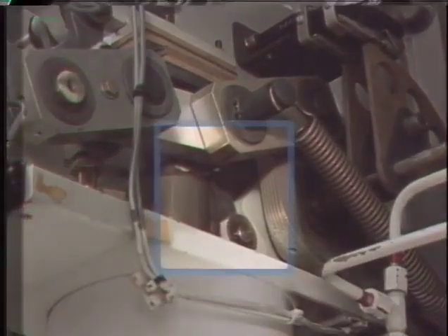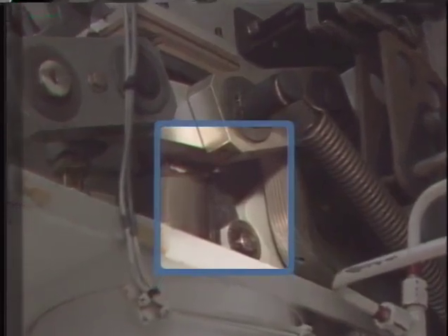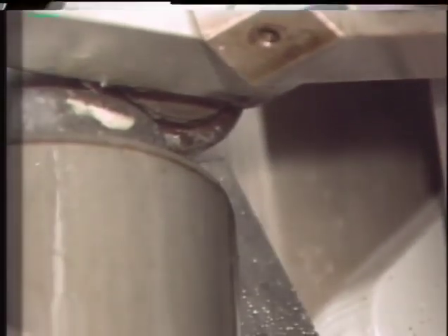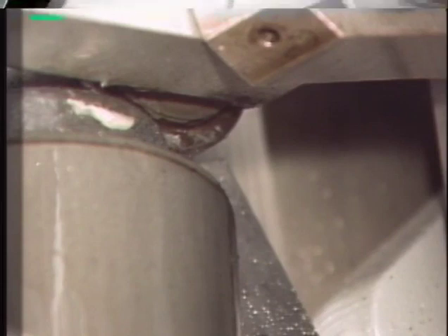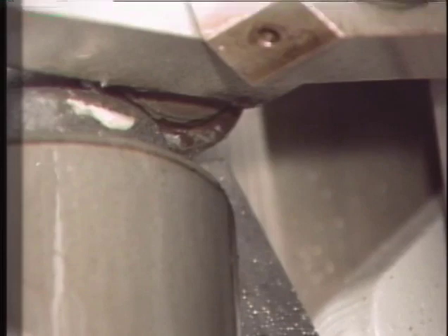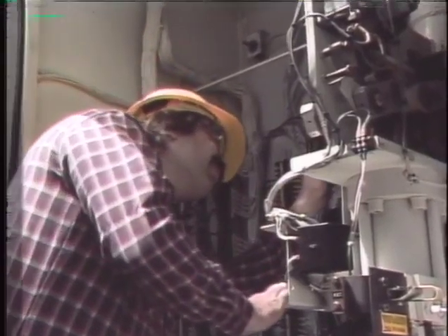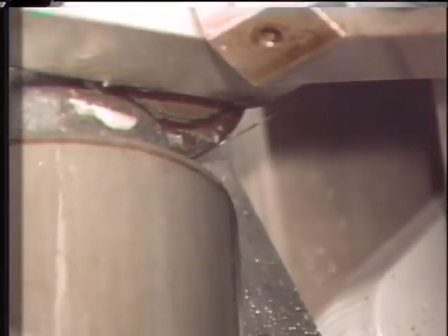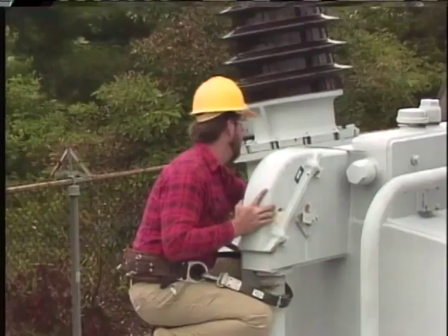Latch clearance is the amount of clearance needed for a latch to consistently drop into a given position. To check latch clearance, start with the breaker open. Slowly close the mechanism so that the latch, such as a holding latch, drops in position to lock the mechanism in place. Then crank the mechanism beyond the latch position as far as it'll go. Then measure the gap between the latch and the surface it normally rests on. The gap should fall within a range specified by the manufacturer or company requirements.